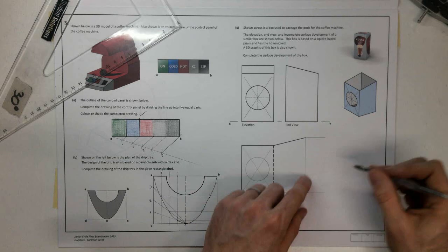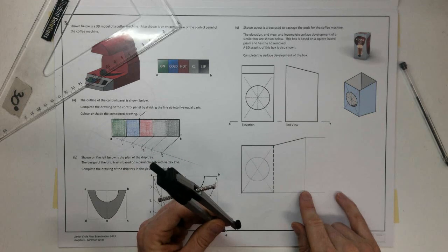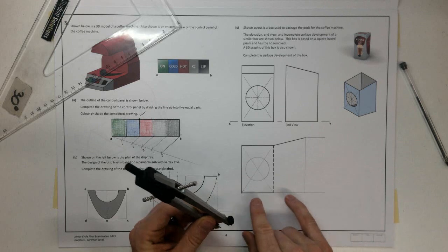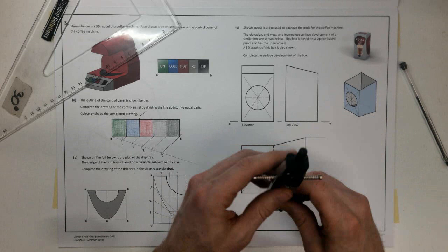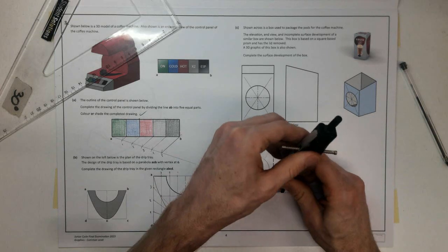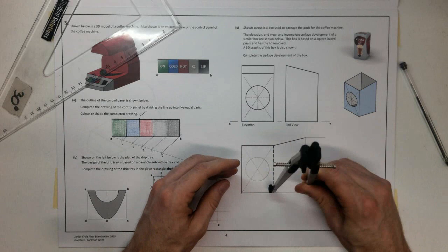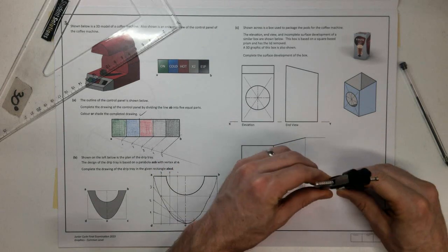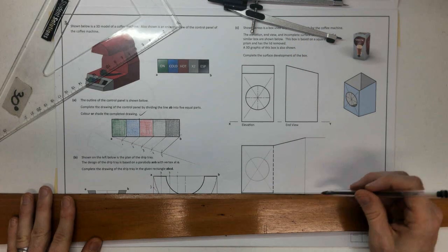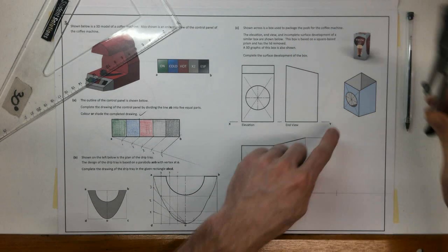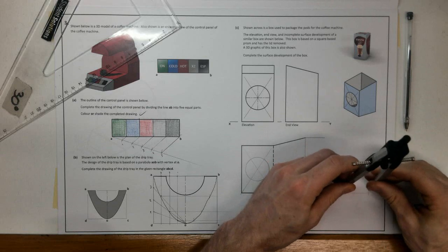So now we're looking at the back. The back is going to be at the same distance because it's a square-based pyramid. So same distance, same distance, same distance, all the way around for each one of these sides. We get the compass, set it to that length, and you can see there it's the same length and same length again. And while I'm here, I'm just going to repeat that because the last side will be the same also. So we've got our division there.